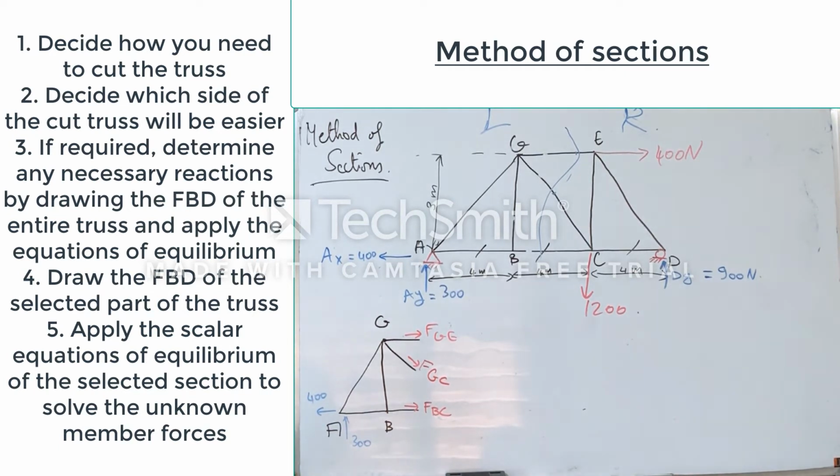And this is, guys, an advantage of this method over the method of joints, because I can directly predict if my member is in tension or in compression. I don't have to flip it. I know that even in the method of joints, I can directly know, because in fact, if I know that the joint is in compression in this member, then this member is also in compression. But here, guys, I'm showing the internal forces directly on the members, okay? So these are my forces. I only have two reactions, so I only have two external forces.